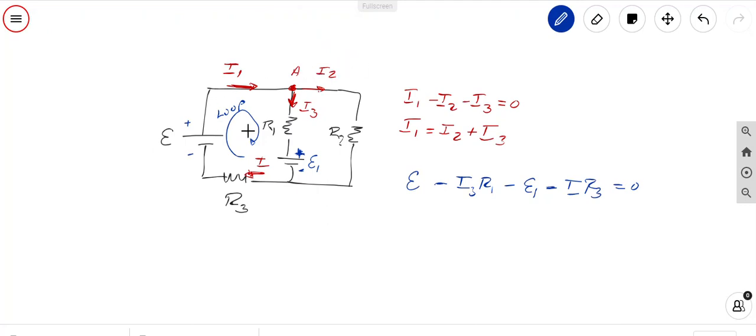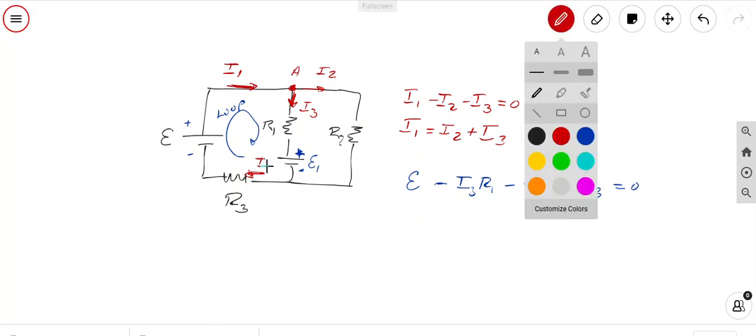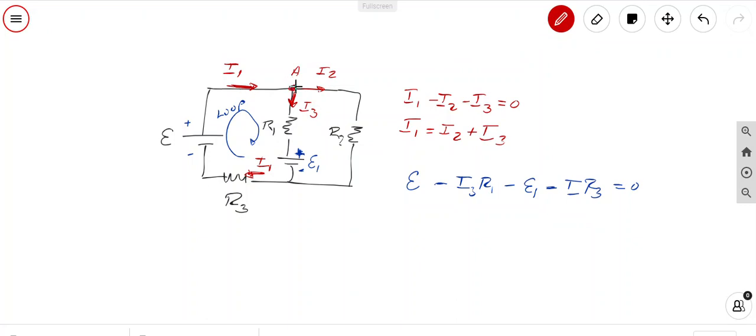it. So, for example, in the circuit that I have here, I have this current I1 that is entering into the junction A here, right? And when the current I1 reaches the junction A, it finds two different paths. So this current will not be split 50-50, you know what I mean? Not just half to one branch and the other half to the other branch. It depends on the resistances that are involved here and all the other components.